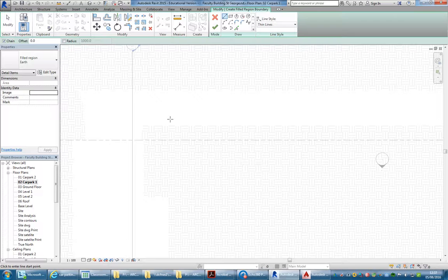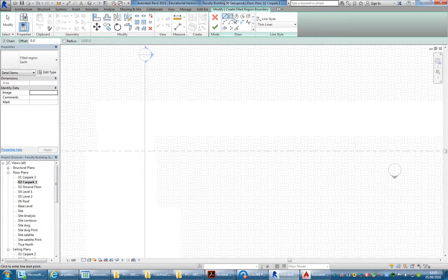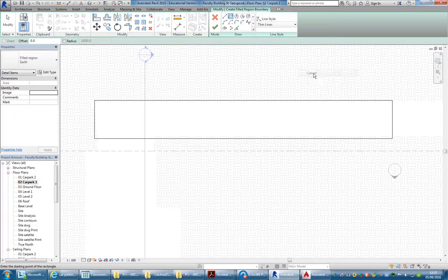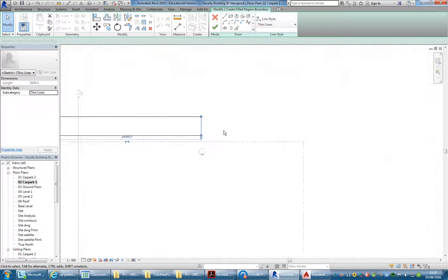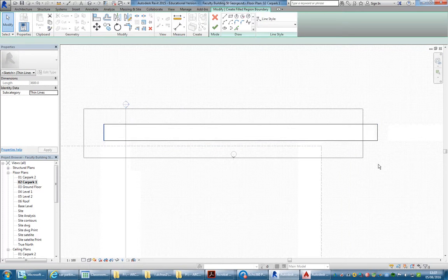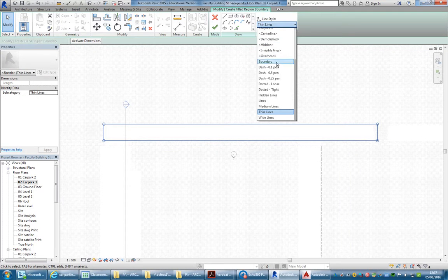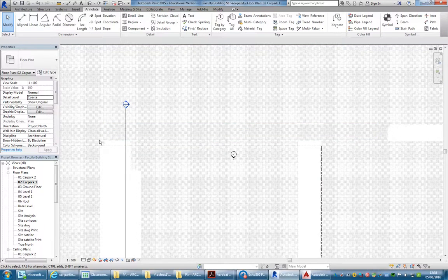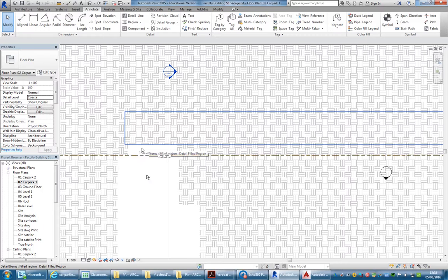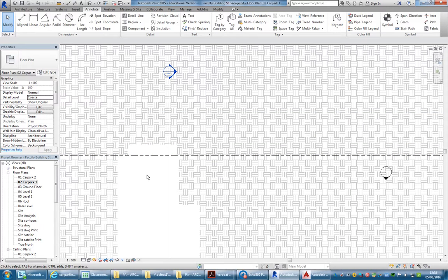And there we are. It's a bit hard to see on screen, but the pattern is there. And so worst case, I can always just draw regions. So I'll just do a quick one there and make sure it's got invisible lines. Okay, and it'll blend in perfectly with any other hatch patterns. So worst case, that's always a solution. And it's important that you have that because you will have retaining walls that need to show the earth on the other side on those levels.